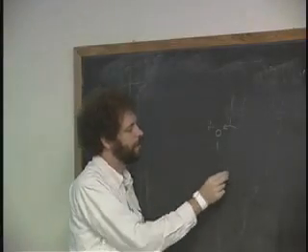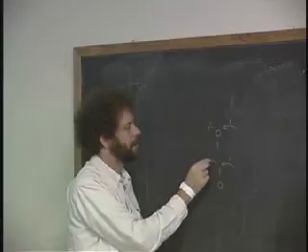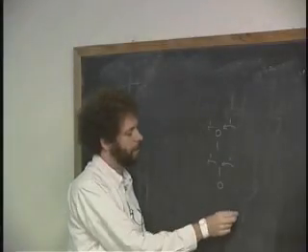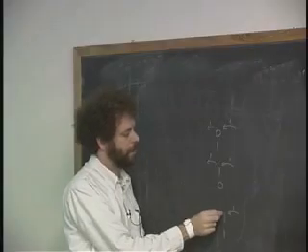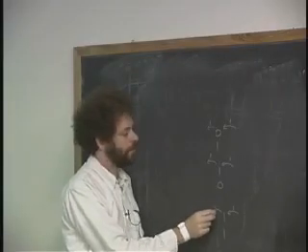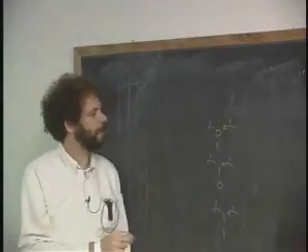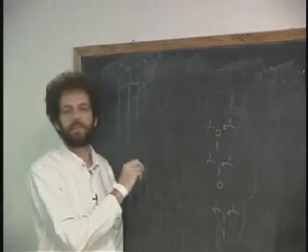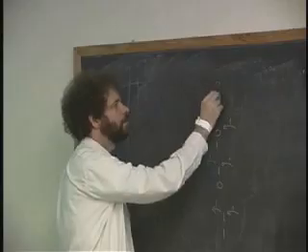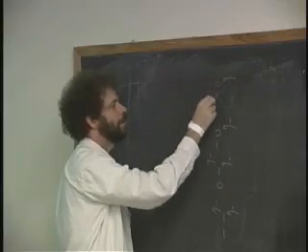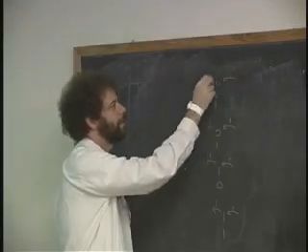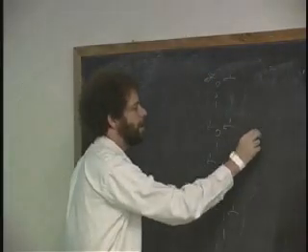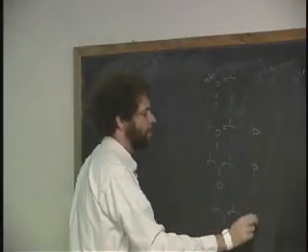Obviously, if a 1 and a 0 comes in and a 1 comes in, then I want to propagate out. What about the 1 and the 1 case? If a 1 comes in, should I propagate the carry out? Yeah, okay, so there's three cases. And the only one left is 0 and 0. And do I propagate then? Hopefully not, right? If a 1 comes in, then I eat it up and I spit it out here, but I don't propagate it out the output. So here I propagate, propagate, propagate.